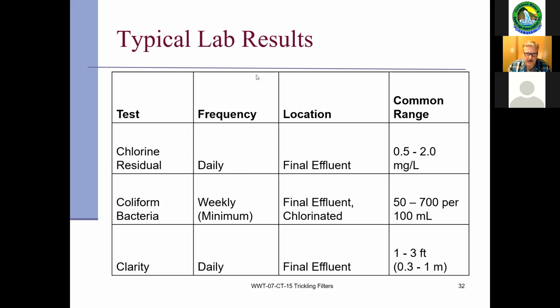Some of the chlorine residual on the final effluent. Obviously, it's going to chlorinate or disinfect somehow before it leaves that facility. Coliform bacteria and some clarity NTU results on those clarifiers as well. Or sorry, not clarifiers, trickling filters.